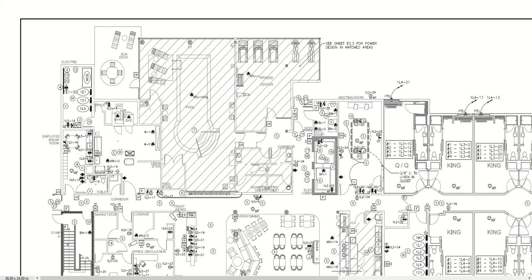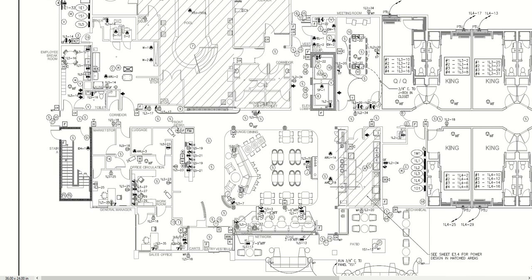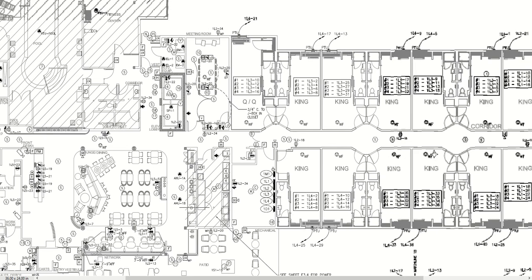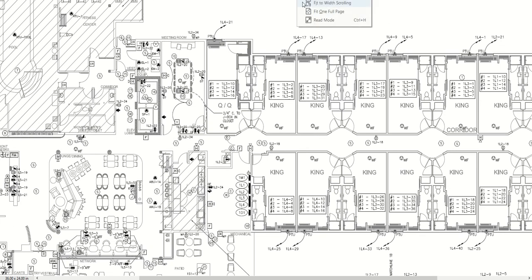So, again, moving down, you can see some more stuff here. There are air handling units in the ceiling, so we have connections for those. We have floor boxes out here in the floor. We have a TV above this fireplace, so we've got an outlet located up there above that. So, again, just common sense placing outlets, and then we circuit them up and see how it all works together.